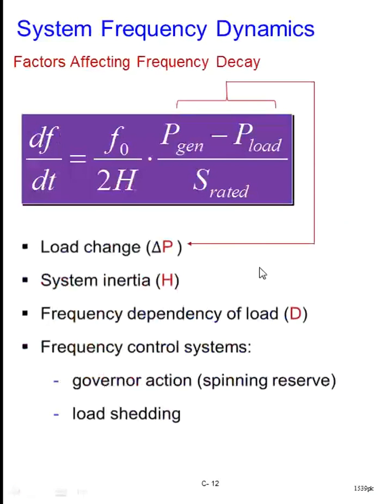as I said, what are the factors that affect the frequency change, that is, the frequency decay. One is, as I said in the previous slide, the difference of power, that is the delta power change here. Another term is the inertia. These are the important terms which are the influencing factors for the frequency decay.